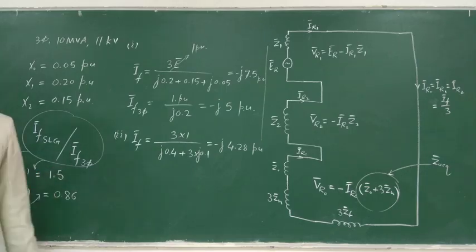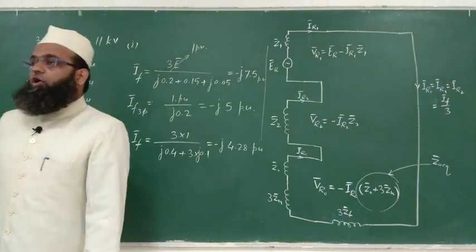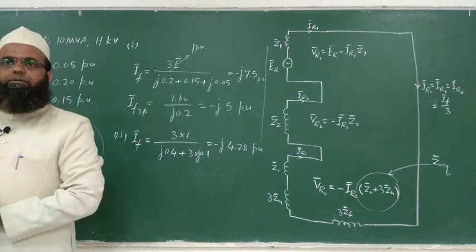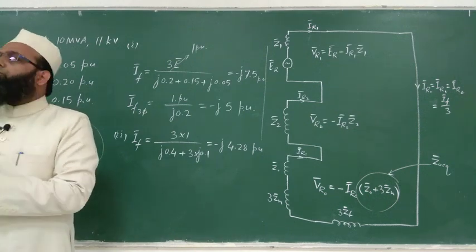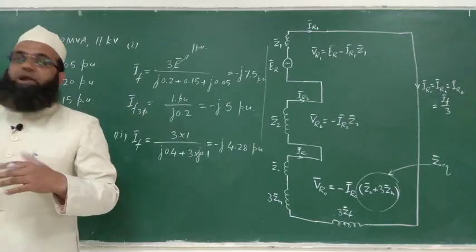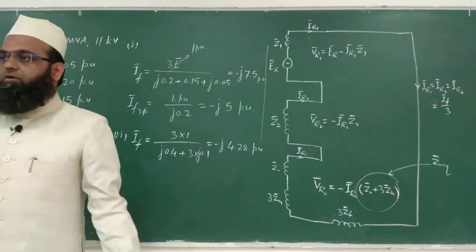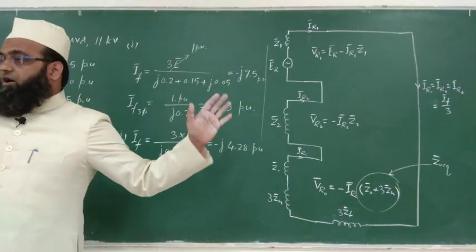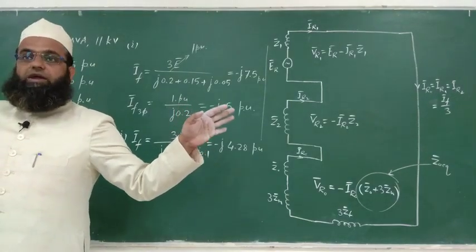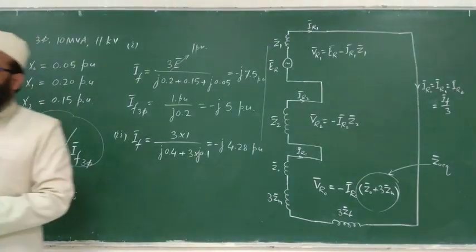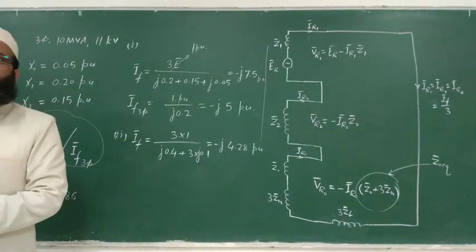But the occurrence of such single line to ground fault and 3-phase fault, mainly 3-phase fault occurs on transmission lines. So if you are talking about probability, the probability of this fault is more, around 50% of total faults, because we are having wide length of lines, right? And for this particular condition, you may take around 2%, 3%.